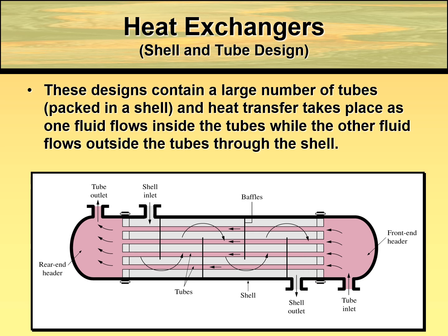This design contains a large number of tubes packed in a shell, and heat exchange takes place as one fluid flows inside the tube while the other fluid flows outside the tube through the shell. A baffle is added into the shell design to increase the surface area and to enhance the heat exchanging process.